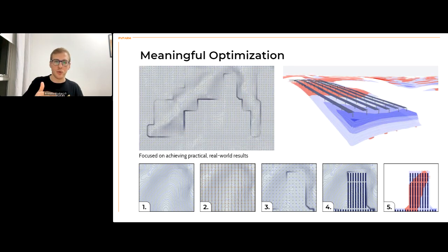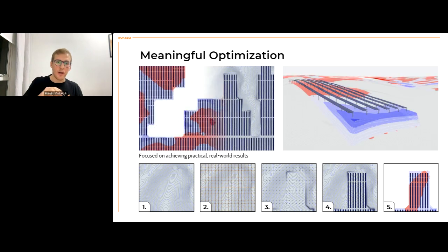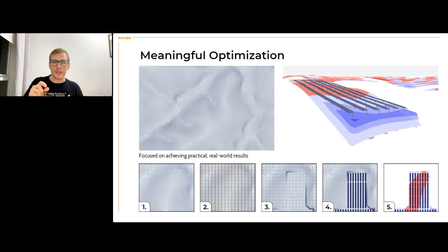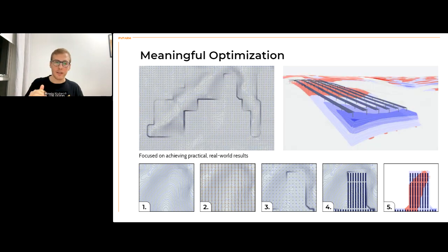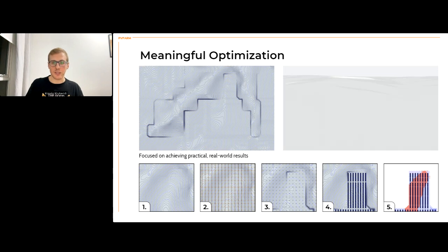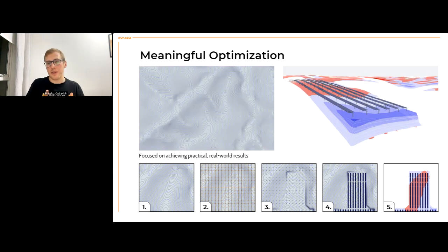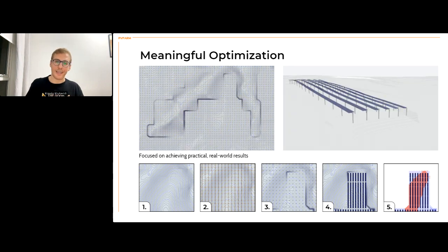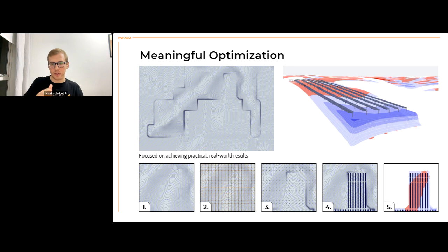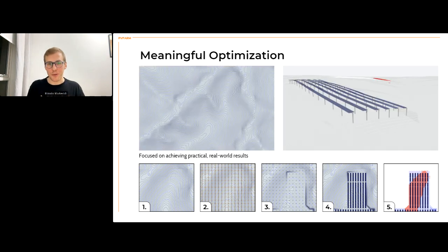So it helps us to actually optimize the terrain on the trackers. So basically, the distance you put there from the module to the final grade is always satisfied. And after that, we also do some analysis to provide a daylight slope, to provide a connection from the graded area to the existing grade area. And that's what we call a meaningful optimization.